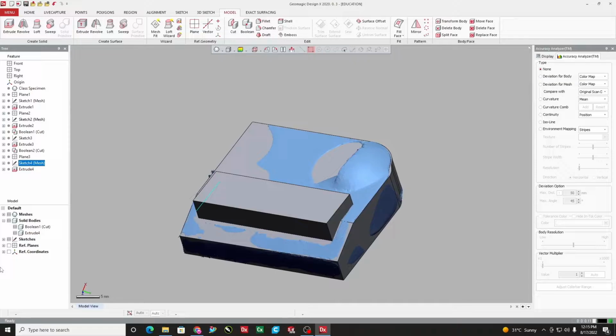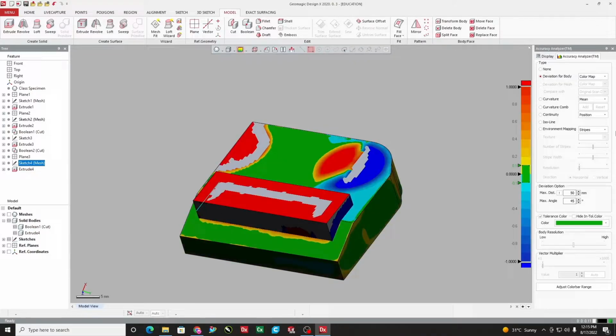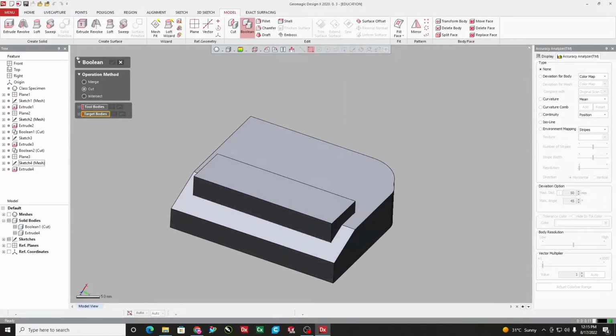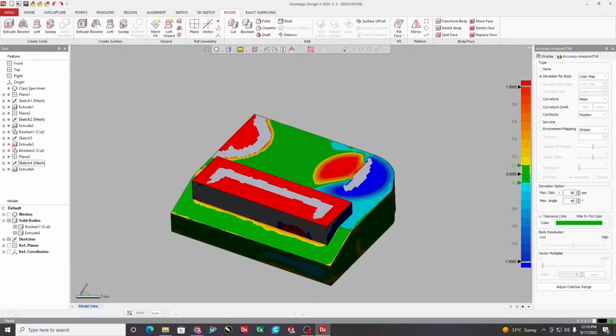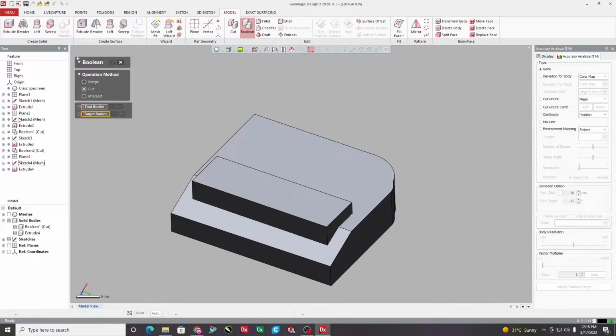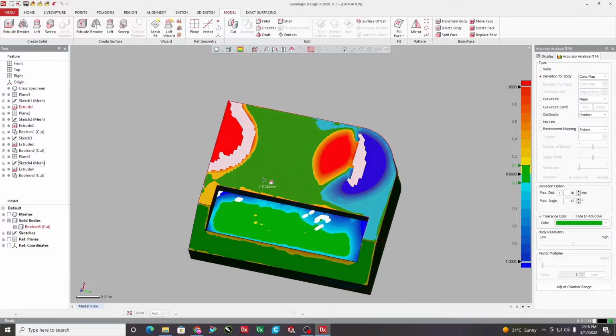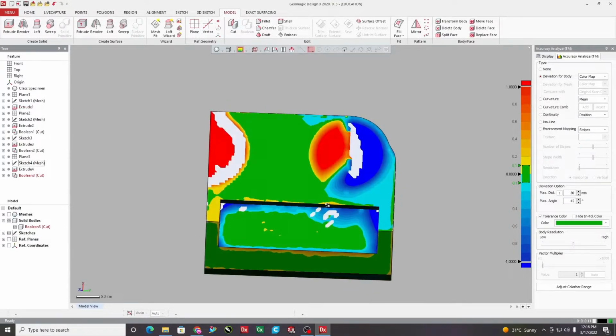and this will now help us to cut the pocket. But this pocket definitely is not showing the fillet or the curved edges. If we now perform the Boolean operations over it, we can again cut it. So we'll cut it. It is showing right, intersect. The tool, merge, cut, intersect. I'll select tool, select the material. Right. Previously the options were swapped. It just cut, the tool was selected as the material and the material was selected as the tool. So now it is corrected.